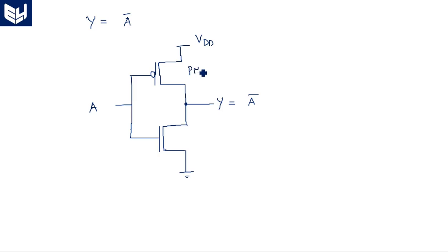So this is a PMOS transistor and this is an NMOS transistor. This is the source terminal, the NMOS transistor source terminal. As it is the beginning circuit, I am representing the arrow also for your convenience, so that you can understand which is the source terminal and which is the drain terminal. Actually, in MOS technology, there is no specific representation of source and drain. You can use either of these terminals as source. It is a bidirectional device.